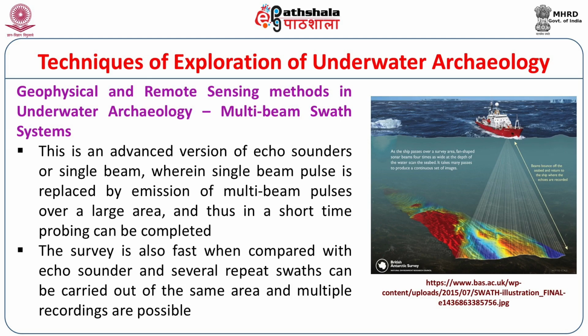One more advanced technique is the multi-beam swath system, because the echo sounder is very time consuming, as it emits only one ray of the sound beam. But here it covers a very huge area, wherein a single beam pulse is replaced by the emission of multi-beam pulses. So a large number of pulses are emitted, covering a very big area, and a swath of the entire seabed can be completed in a very short time.